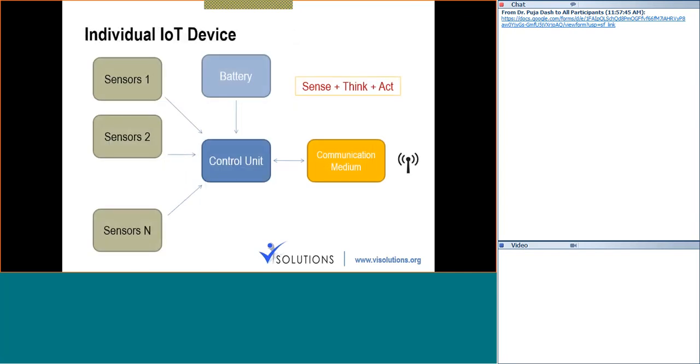So this device might possibly have a battery, and it will have a lot of sensors, voltage sensors. If you have a three-phase grid, then individual voltage sensors and individual current sensors. Three-phase means you have to measure everything individually. The current sensor could be a Hall effect sensor, or it could be a current transformer. It could be anything, right?